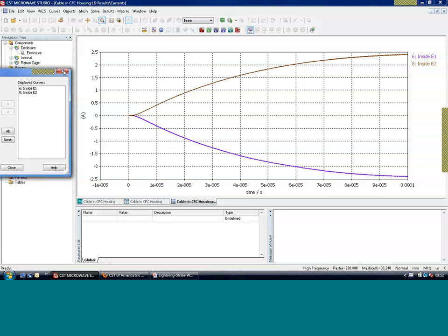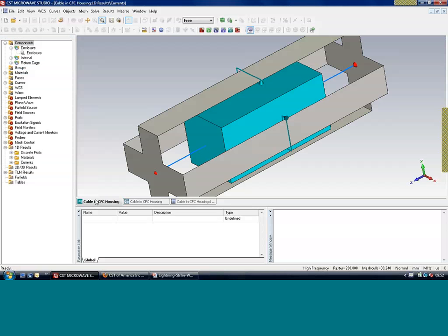Again, as I said, for this example, we've looked at a very simple problem because it's allowed us to really understand the problem quite well, rather than doing a very complicated structure, and to see how these simple changes are making an impact in terms of the results which we see. And in terms of modelling the composite here, we've modelled it as a bulk material property. We haven't taken into account different weave angles, for example, because we're looking at it at a much larger scale than we'd be interested in for going down to that level of detail on the material properties.